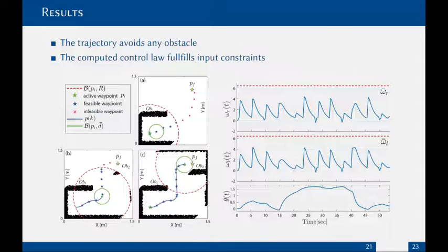This picture shows the joint actions performed by the vision module, path planner and control unit. It is possible to appreciate the capability of the vision system to rebuild the obstacles and the determination of a sequence of waypoints that fulfill the viability conditions. Notice that waypoints are tracked one after the other by ensuring that the robot keeps within the guaranteed obstacle-free circumference centered in each waypoint. It is also shown that the prescribed constraints on the left and right angular velocities are always satisfied.